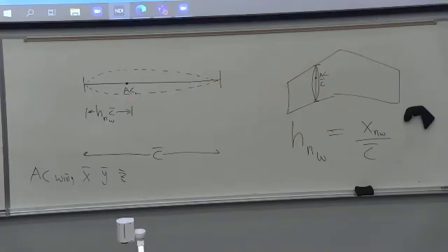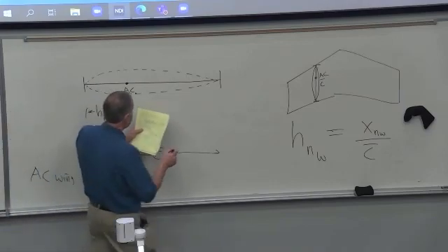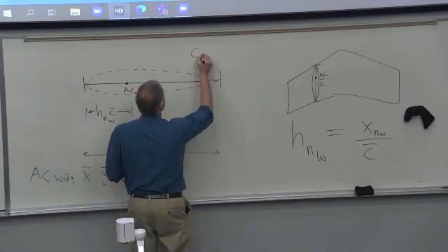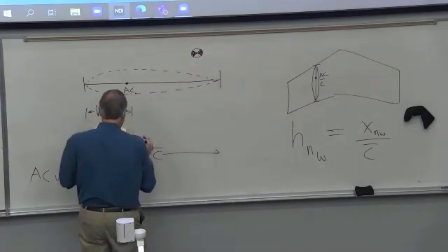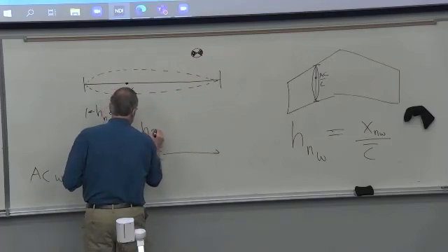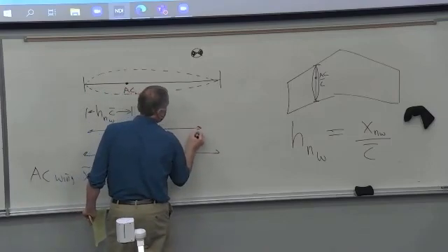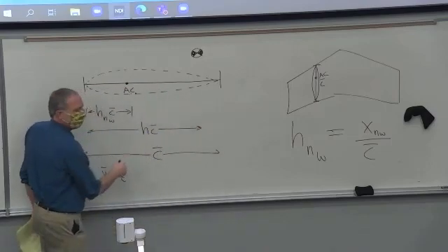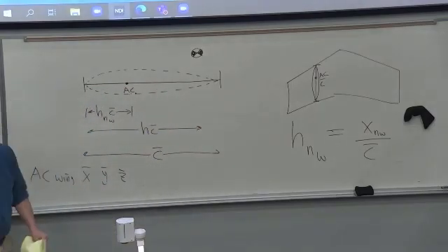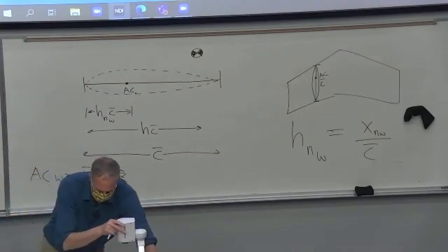Draw that thing in. Step 3, let's put the center of gravity. And we're going to just put it at a generic location here. And we're going to locate that with H. So H is the non-dimensional distance to the center of gravity. Multiply by C bar to get it actually in feet. Let me get this out of your way.